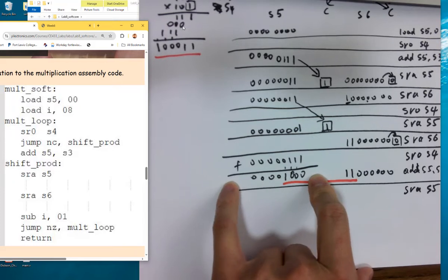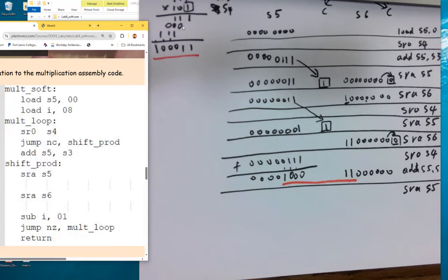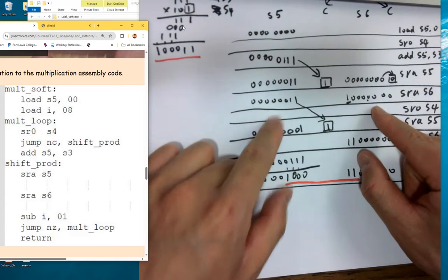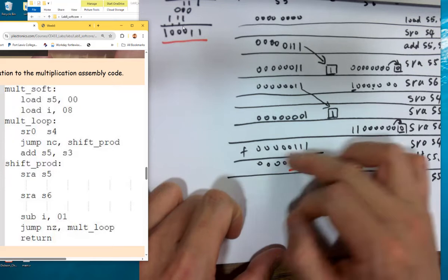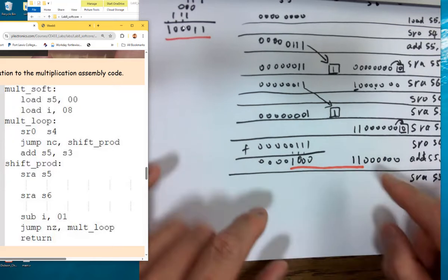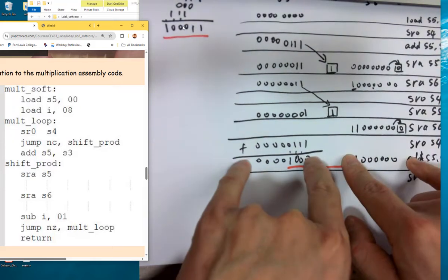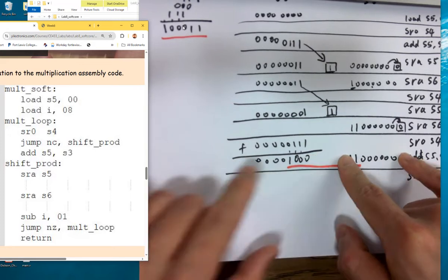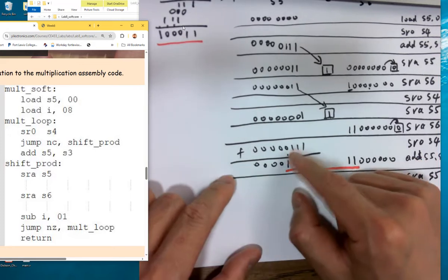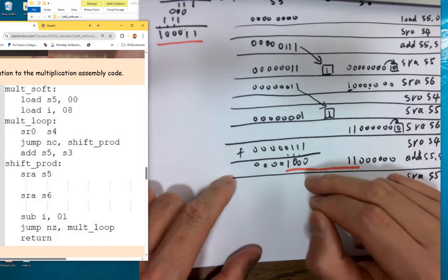In C it's pretty easy, right? Everything is running behind the scene, but in assembly you have to handle the register level operation. You don't have to do anything, just treat them differently. When you are treating this register, you just have to treat it as an upper byte. Eventually these are all filled up with zeros, but just in case you have ones in the upper byte, treat it as the upper byte. You treat these as the lower byte. So whenever you are seeing a 1 here, it has to represent a certain number at that digit.